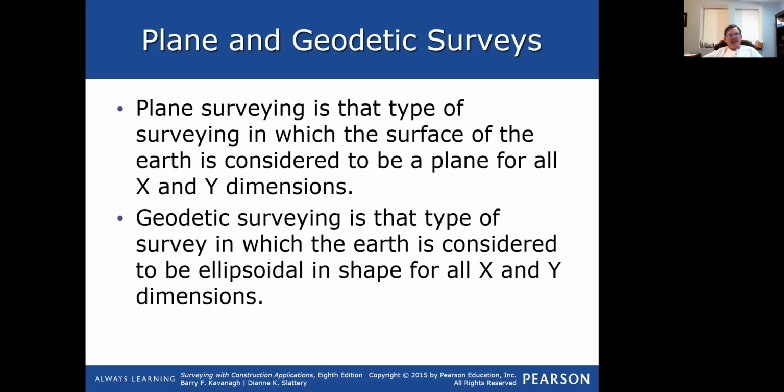You're going to see some terms in your text, if you haven't already read it, called northing and easting. Surveyors take a geodetic measurement. Most of my measurements, I can have a latitude and longitude assigned to those measurements. I start with satellite receivers, and those measure latitude and longitude, and that is converted to plane surveying, a flat table.